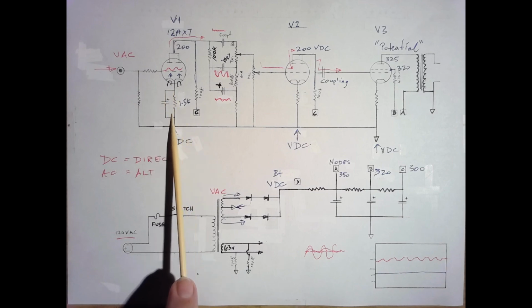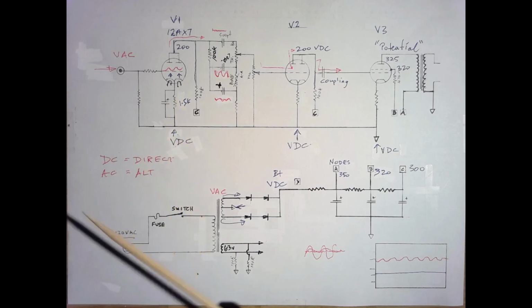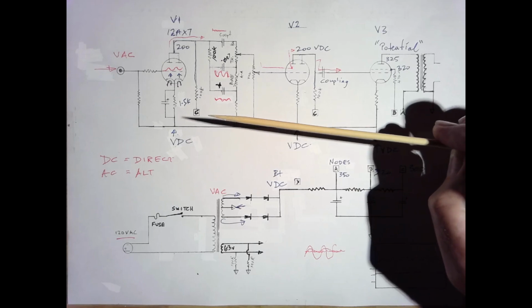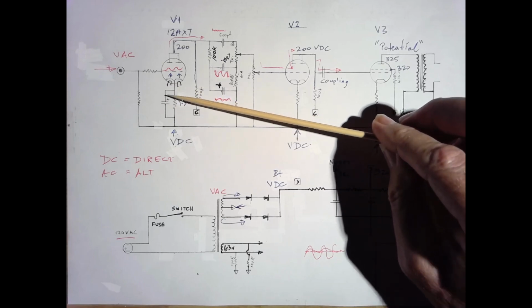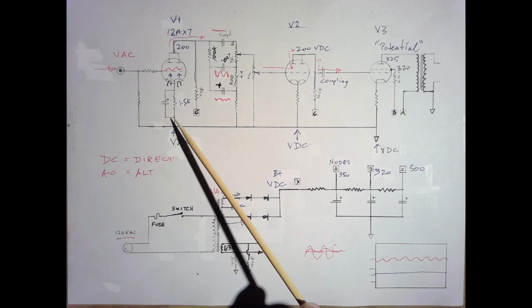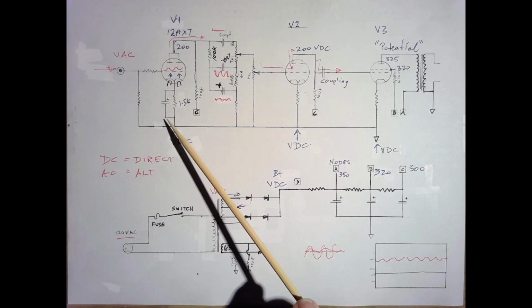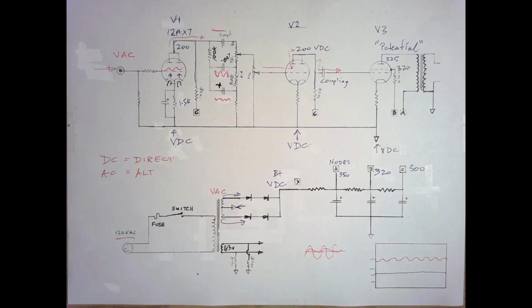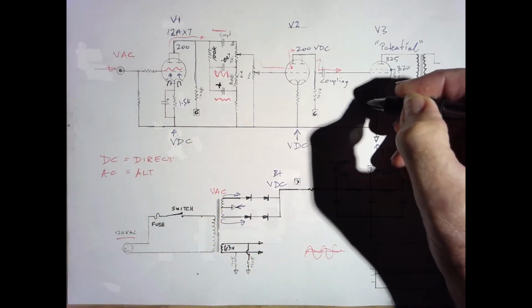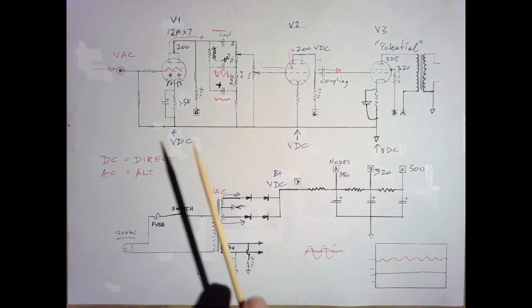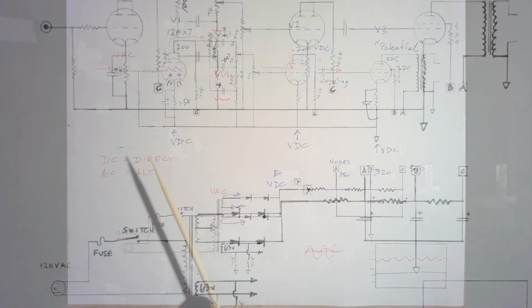and we have a bypass capacitor. So how the bypass capacitor works, this is kind of a fun experiment. If you have ever experimented with an amplifier while it's powered up, hopefully in a very safe manner, and attach and connect and disconnect this, you'll hear a drop in gain when it's disconnected. There's usually also one down here on our power tube as well. It allows a lot more gain in the tube. And why?